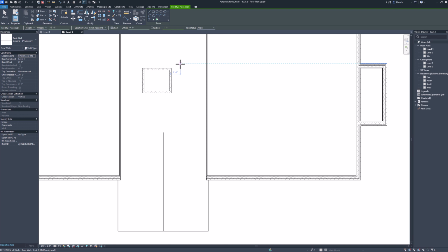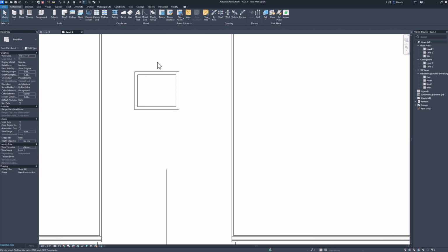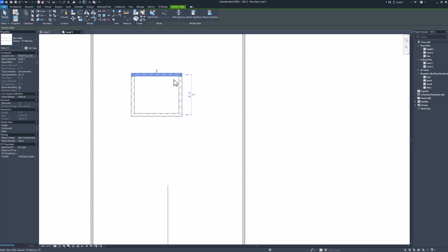Right click, cancel. So it says that our elevator shaft, the inside is 7'4" by 6'10". So which dimension is the 7'4"? Okay, yeah. I'm looking on the next page, so let me cancel out of this again. So I'm gonna select this wall here. I'm gonna move my temporary dimensions to the inside here. So this part is gonna be 6'10".